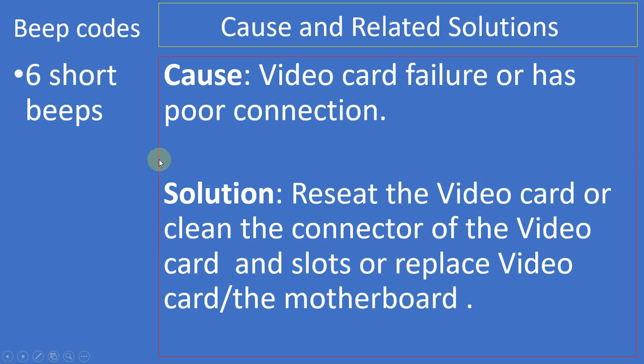So when you hear 6 short beeps, the cause may be video card failure or a poor connection. It means that maybe the video card has failed totally, or it is connected improperly. That means the poor connection. So the solution is to reset the video card.